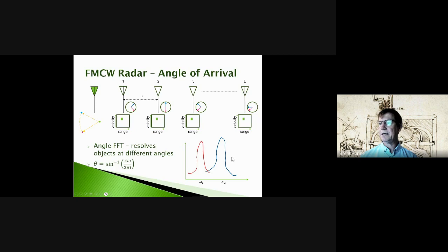We'll look for peaks. You might have some sort of thresholding operation and then try to zero in on that peak, looking for an inflection point where your slope changes from positive to negative, or some other peak detection algorithm, and identify peaks of interest.